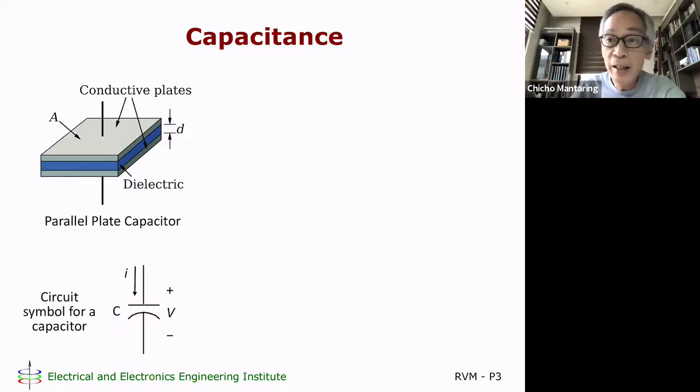And just like any other passive element, like the resistor, which is a passive element, if the current flowing through the capacitor is in this direction, then you encounter a potential drop in the direction of the current, meaning to say the charges transfer energy to the capacitor.